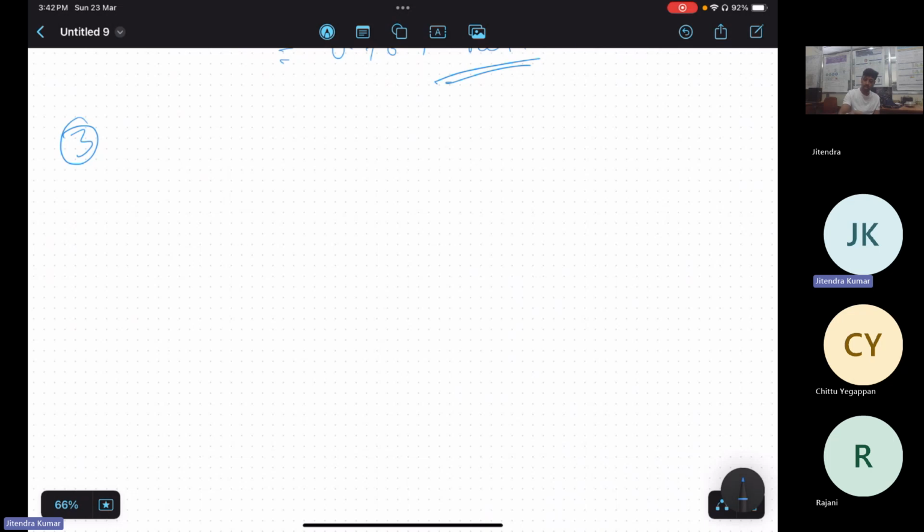Okay, so here it is mentioned that the total SRM is 8 by 6. First, the configuration is 8 by 6, right? 4 phase. If 8 slots of SRM or 8 stator poles are there, so basically it can make either 2 phase or 4 phase, isn't it? So you cannot make 3 phase out of it in SRM because it is concentrated winding.